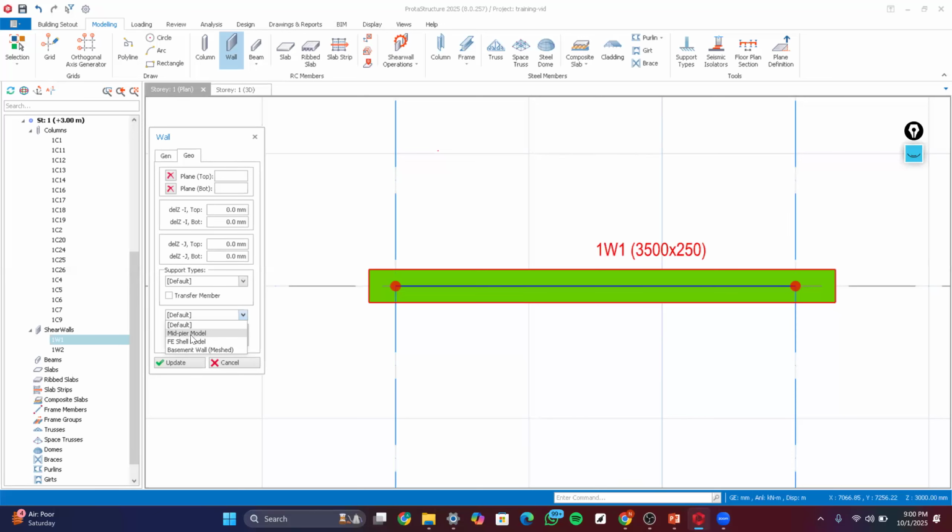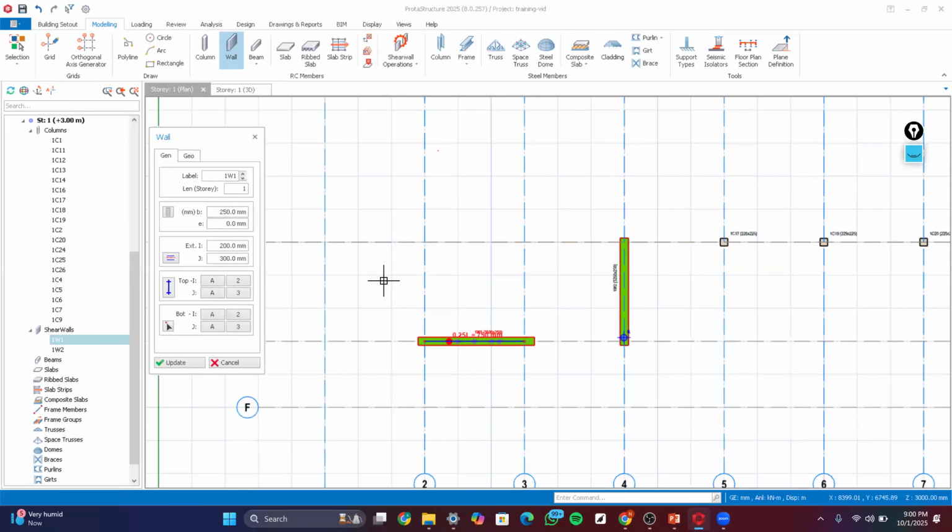Okay, that is where you usually have your elevators, because the walls around that place are actually made of reinforced concrete. And here we have finite element shear wall, and then we have your basement wall. So the basement wall is the option that you select if you are modeling a retaining wall. That is when the wall is going to be supporting lateral earth pressures, or lateral loads from earth. So here we are now going to delete these walls.